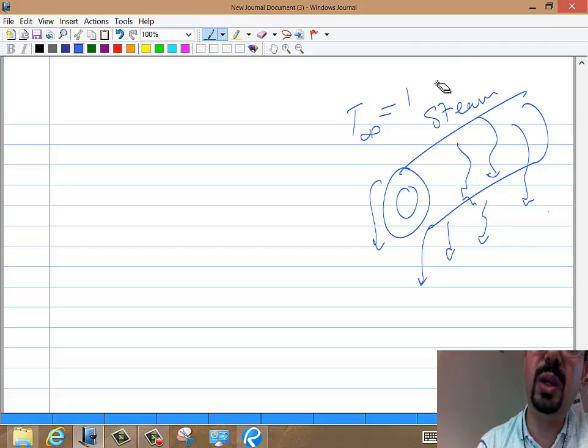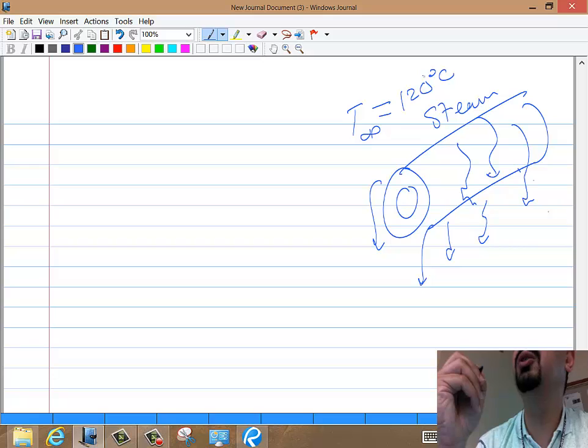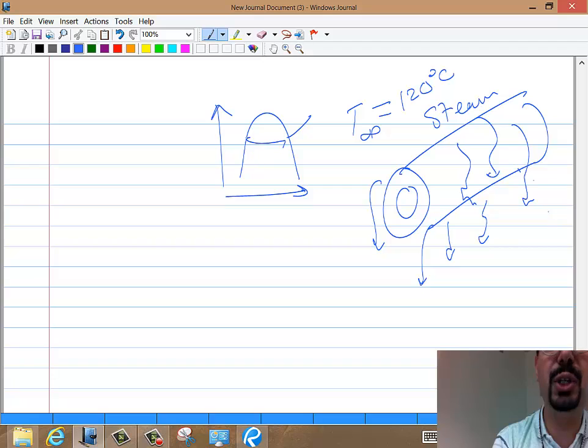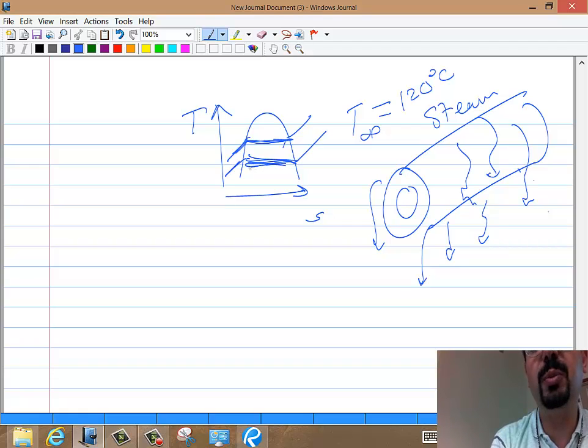So of course, why is it not condensing at 100 degrees? I thought that water was boiling at 100 degrees. Why 120? How is that possible? The pressure. There is a whole T-s diagram associated with this, right? And so really it depends on the pressure. The pressure where this thing is at, that's when it will boil, right? So if it's 1 atmosphere, this is the T-s diagram. So your pressure will determine when you would be boiling, right?